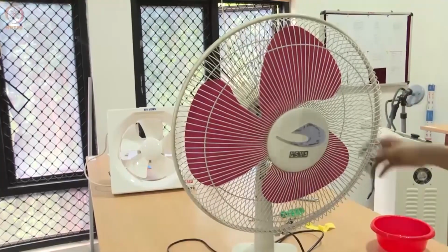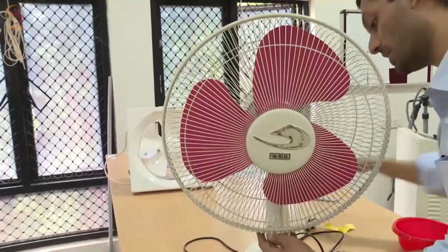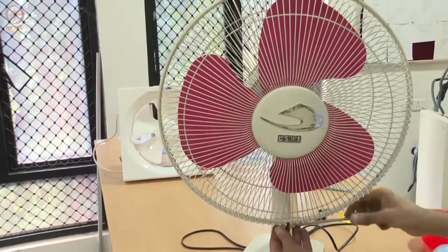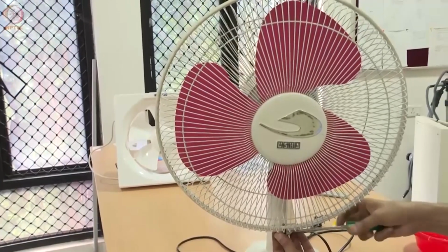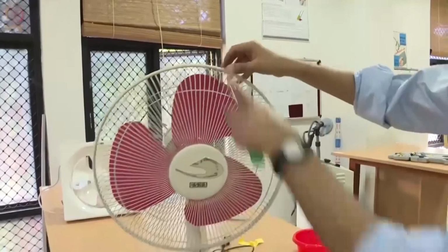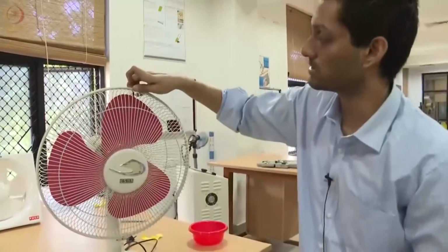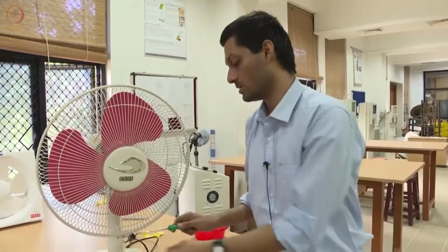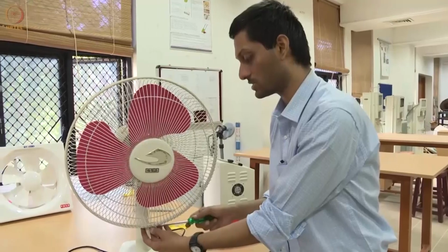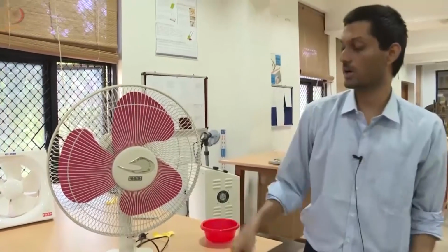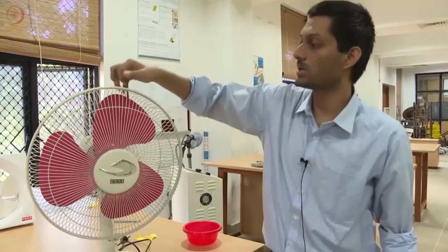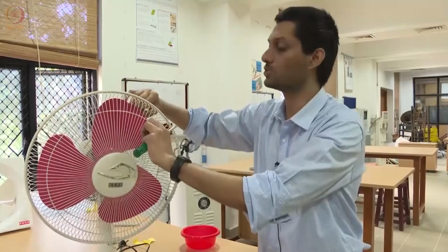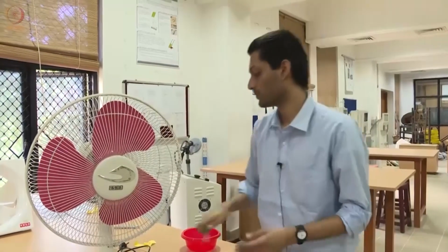So that's it. Now I have the ring properly engaged. All I have to do is tighten the screw to complete the assembly. So now it is secure. Just make sure it is properly secure. After you have tightened, make sure it is tightened by hand as far as it goes. Don't over tighten it. Just enough such that the ring is properly secure, such that it holds both the pieces together. You can maybe give it a slight tug to ensure that it is safely assembled.